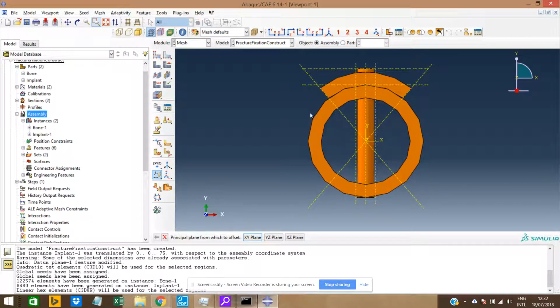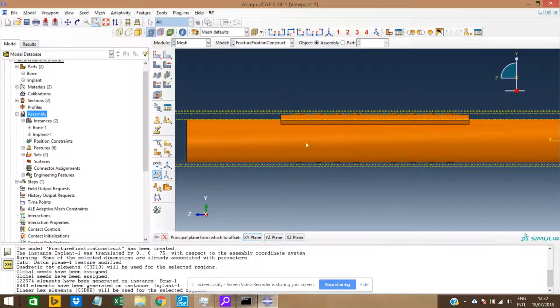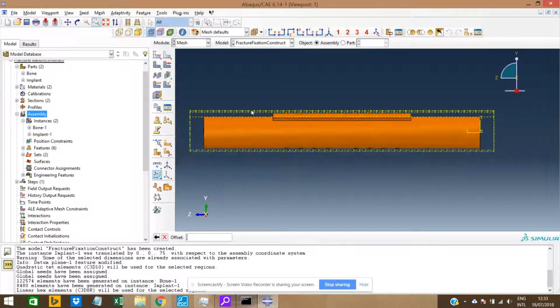Okay, so the other thing I want to do, I'm gonna go on the side here, and in order to enclose those screws, like I said, and also cut them in halves, because then they're in 4 sections, the screws, and well, that just produces a nicer mesh. So I'm gonna start with another plane in the X, offset from the XY to 75, actually, it's all going from here.